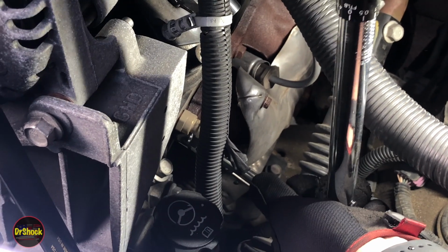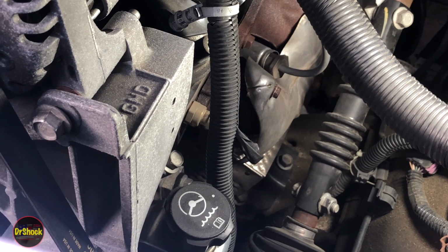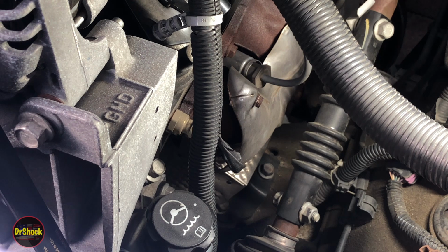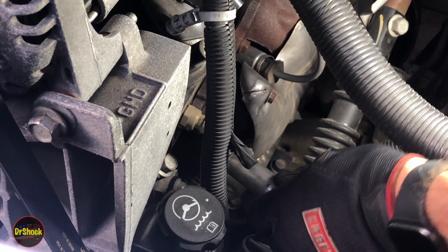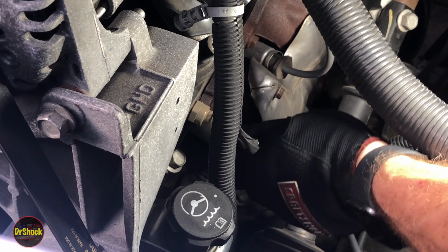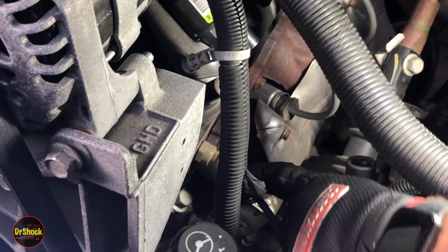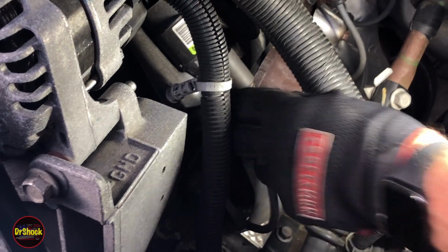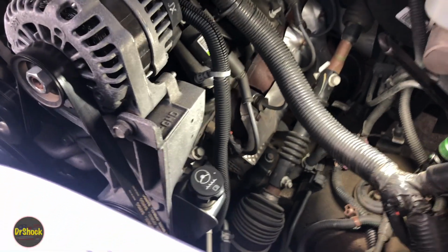Now, is it this easy all the time? No, and it might not even be this easy this time. But we found a problem, and so we're going to correct it. We don't know if we found the problem yet. So let's go ahead and put this wire back on, even though we know it's out of spec. Make sure you hear it click. Now, we're going to take this back off and put some dielectric on it after we do this test, but for now we're just going to pop it on without. Make sure we hear this guy click up and get back to where the witness marks are. Let's go ahead and fire this engine up and let's see what happens on our Tech 2.